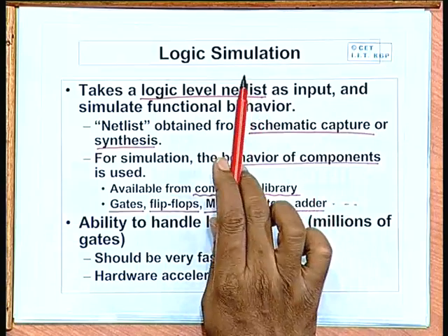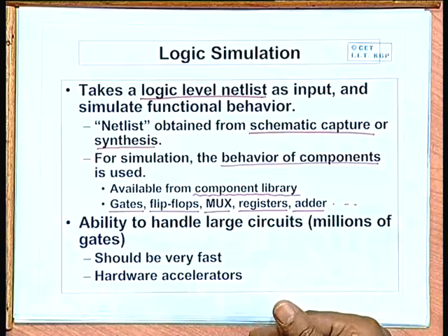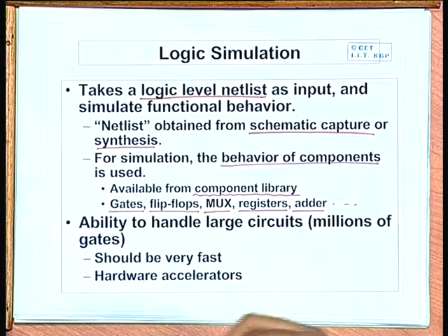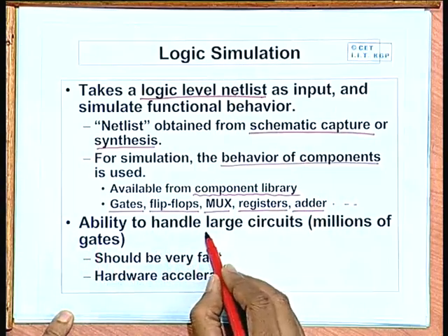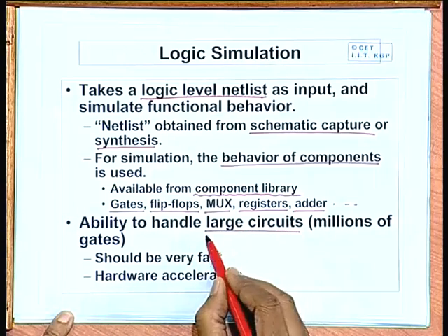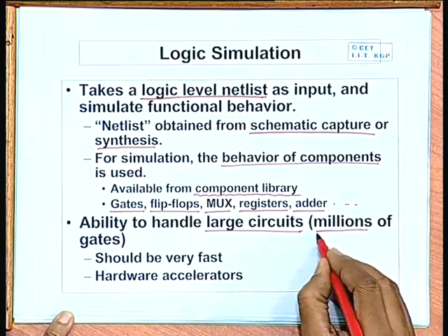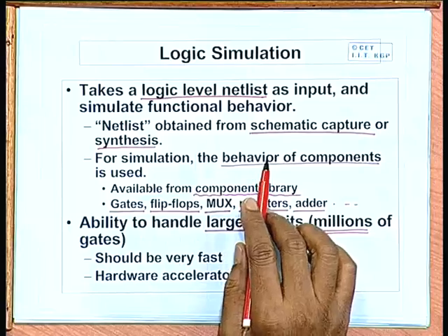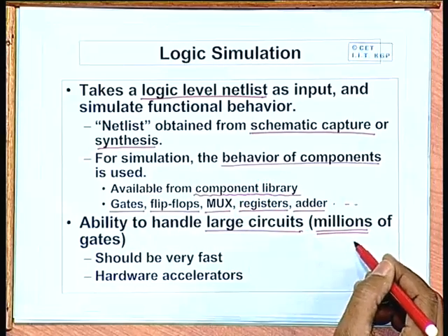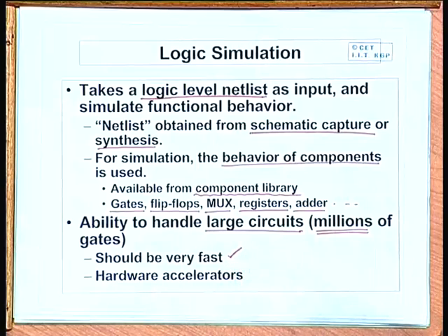Now, logic simulation is used before we go to the physical design. One of the requirements of logic simulation is that it should be possible to handle large circuits. In the present day scenario, large circuits means millions of gates. So the logic simulation process should be very efficient and relatively fast, able to handle circuits of the order of millions of gates.